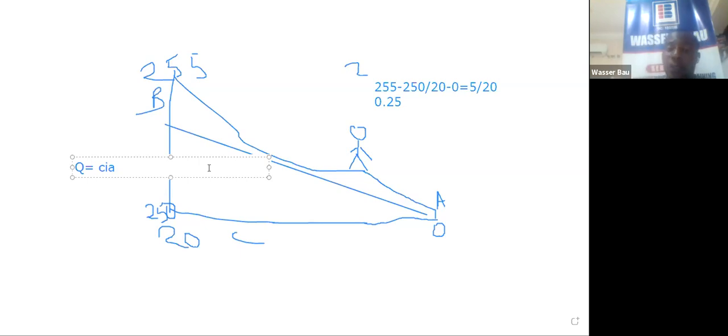Then for the second question, it's a very beautiful question. When you want to calculate your Q, this is very simple. Number one, the first thing you know for your Q is the water demand, which we call Q subscript W. Sorry, I don't know how to write the subscript W here. Your Q subscript W could be, let us use, 100 liters per capita per day. Then from your table, which I'm going to show, you choose a safety factor, or what we call the peak factor, hourly peak factor.